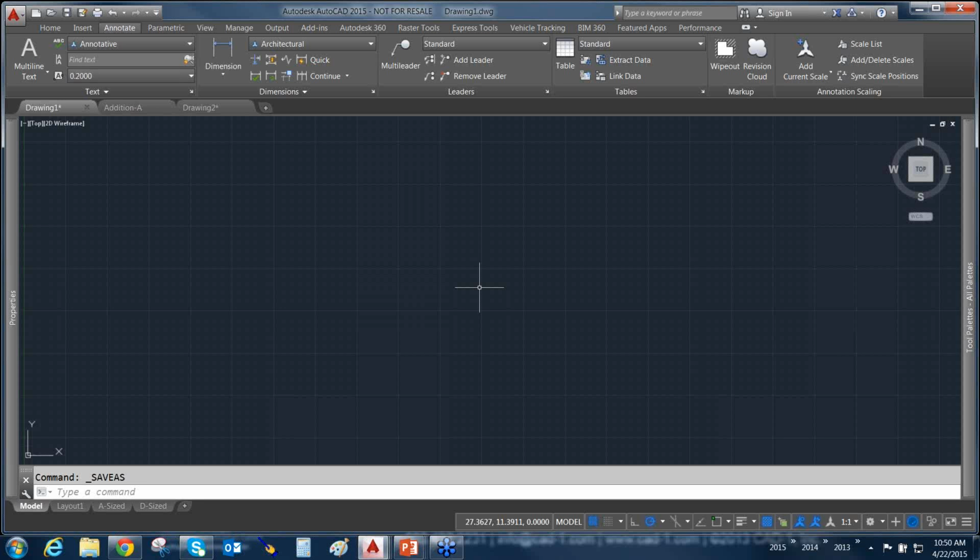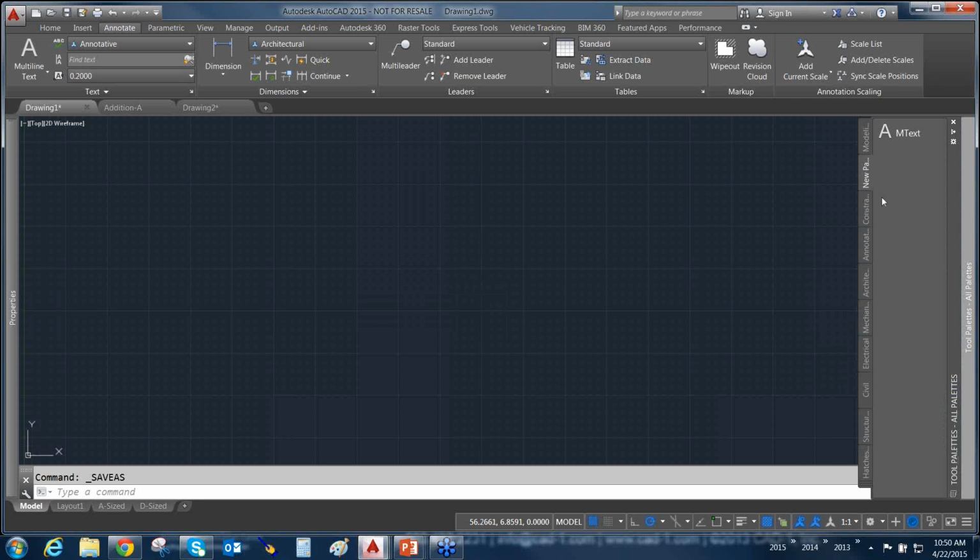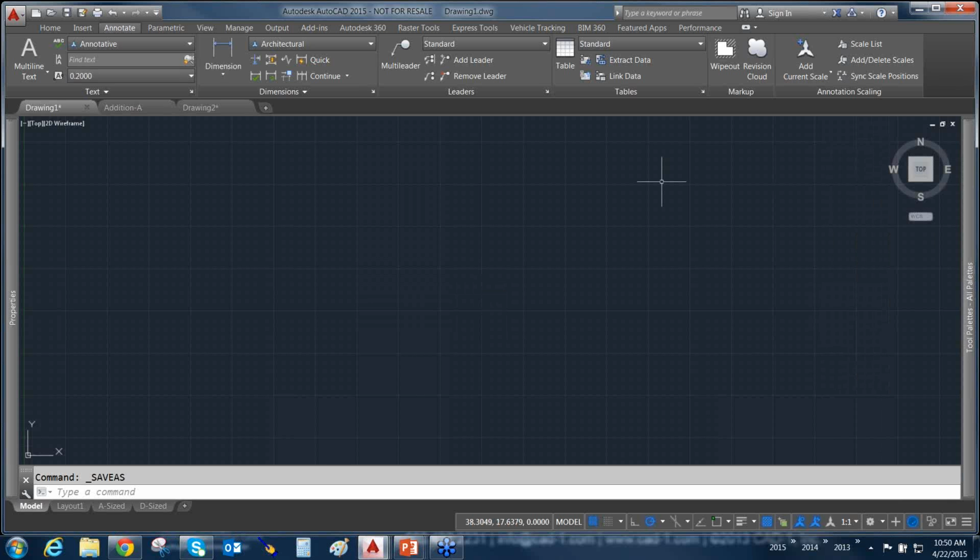So yes, purging reg apps, I've actually built it as a button in a tool palette somewhere, and I just have the users go in every so often and click that button to automate the task and purge the reg apps. There's no reason to keep reg apps. Purge them, keep your drawings clean. If your drawings get too many reg apps, it could cause the drawings to become unstable, or at the very least cause AutoCAD to slow down your performance. So yes, you should. It can be a big bugaboo. It's one of those mysterious things. Why is this doing this?